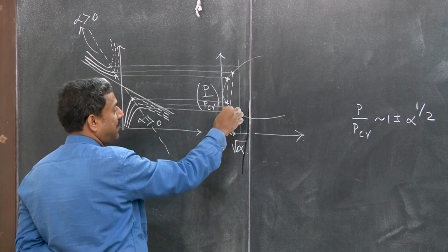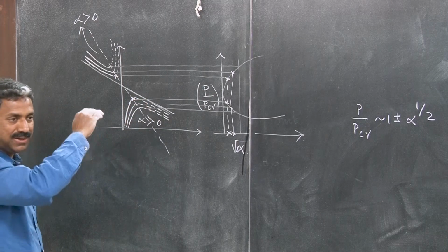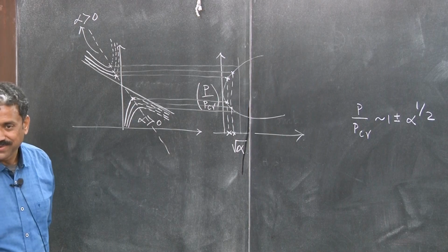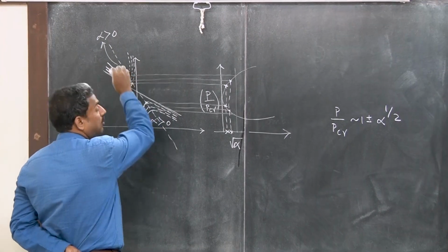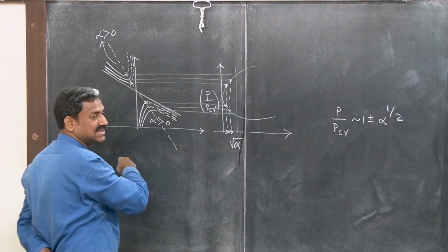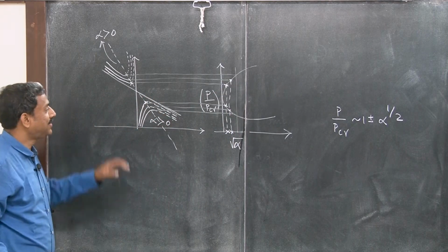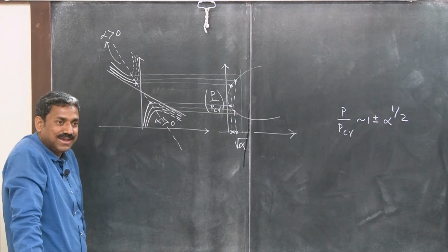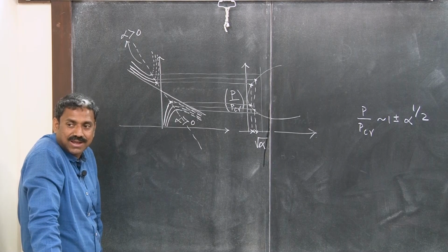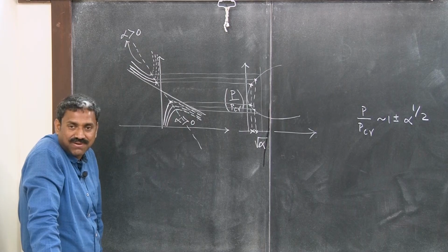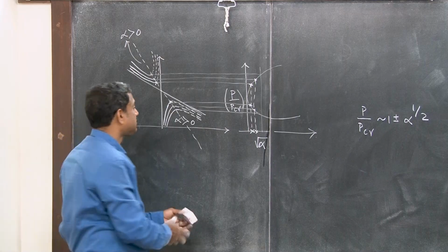Similarly, for this one, plus minus alpha, in this branch the load is decreasing, because you see these points are the limit points. So, from the limit point the path is going down, so the load becomes imperfection sensitive. But if you go to the top, the load will increase, because it is imperfection insensitive. So, that is why it is an upper limb. Similarly here. So, what I just wanted to show you is this correspondence, okay, the correspondence between the stability diagram and the imperfection sensitivity diagram in case of asymmetric bifurcation with stable unstable behavior, okay. Please note that.